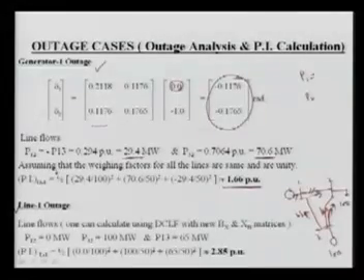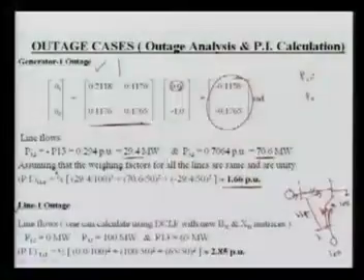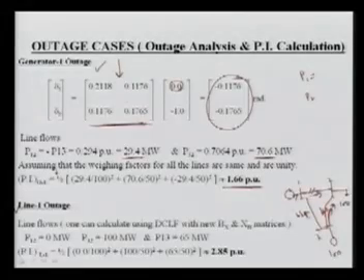This matrix is revised because this matrix is dependent on the line topology. So if a line is going to be changed, if a line outage happens, then this matrix will also change. In the previous case, this network was intact, only a generation outage, so we only changed here. In this case, with the line outage here, this value is the same, so we take 0.65, and here we are getting 1.0 with the negative sign, so it is not going to change.